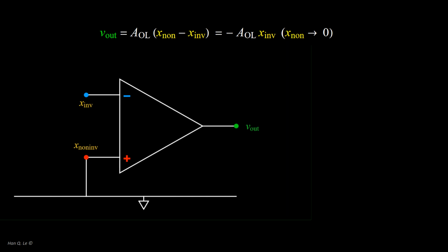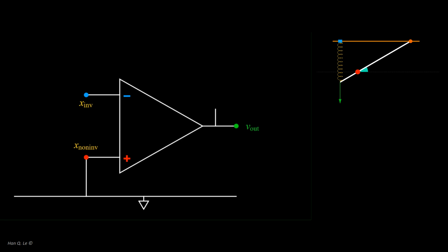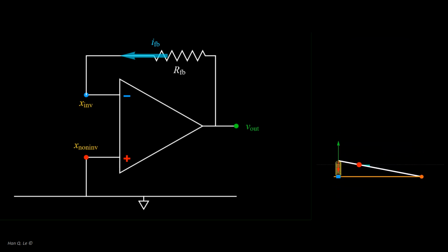Next, like the mechanical arm that lifts a lever for negative feedback, the output is connected to the inverting terminal. How much feedback, like the coil in the mechanical model, can be controlled with a resistor, which is the feedback resistor. If the resistance is infinite, it is the same as without negative feedback. Hence, the lower the feedback resistance, the stronger the negative feedback. In this sense, the feedback resistor is like the coil in the mechanical model. Lower resistance is like a stronger coil.